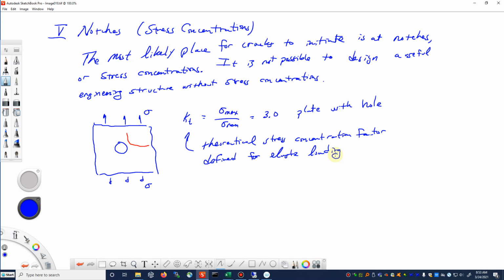So it's the thickness of the plate times the net horizontal distance, that minimum there. In other cases, the nominal stress may be defined on other sections. So you always have to look at the stress concentration factor chart in order to determine how that nominal stress is defined. But however it's defined, you should end up, for the same geometry, with the same maximum stress.